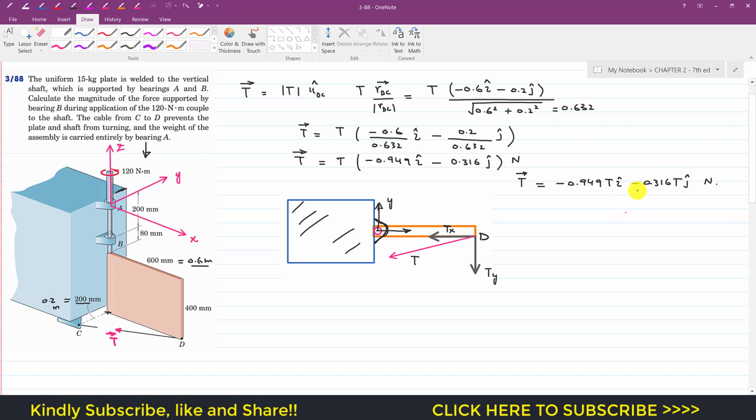So now if we look into this, as we can see that this T is passing through that point A. Let's assume that this Tx is passing through that point A, since we can neglect the thickness of this plate. If we neglect this thickness, the moment of this Tx about that point A will become 0. So we can say that this Ty is only producing the moment about that point A.